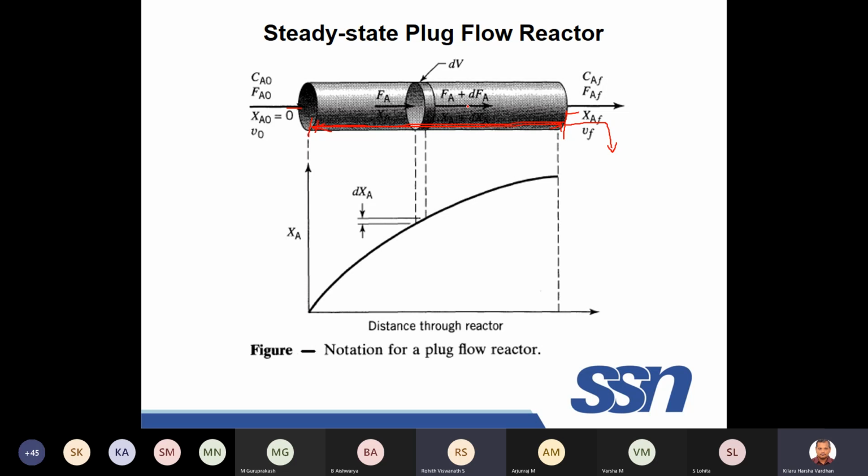then what is the difference between a batch reactor and an MFR? Both look the same, right? So this is the reactor, this is the volume, this is the stirrer, this is the inlet, and this is the outlet. In a batch process, this is not there, this is not there. In a continuous MFR, this is there, this is there. The reaction is happening in the same vessel, right? So then your batch reactor and MFR should also be the same, right? Does my point make sense?